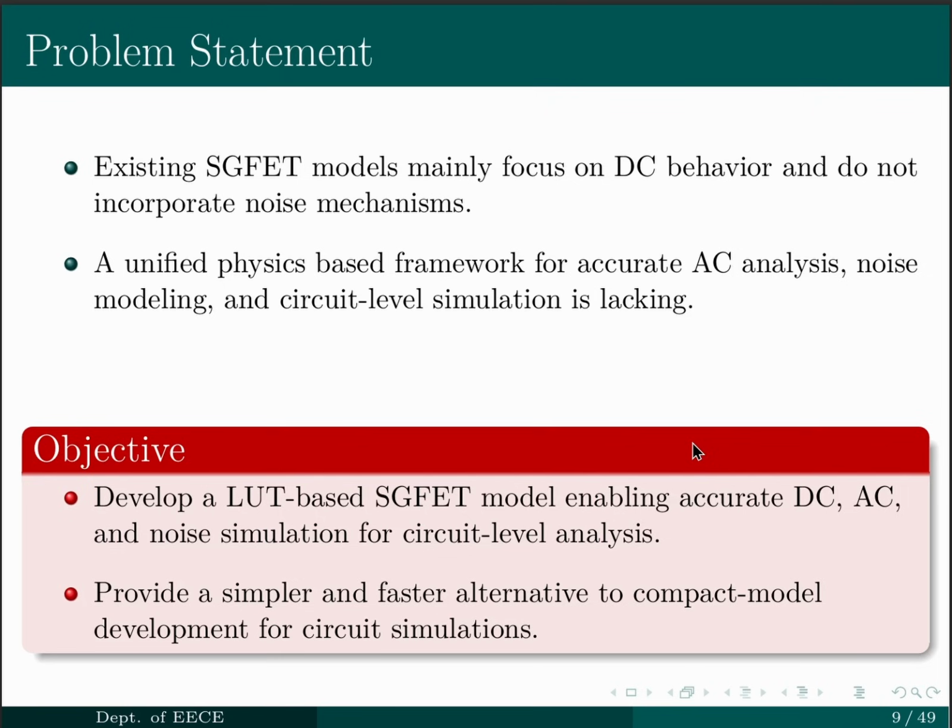And how is it going to be modeled? First, the LUT based SGFET model is going to be developed, which will be simulated for the DC, AC and noise simulation, and for the circuit analysis. The LUT model is used because it provides a simpler and faster alternative to develop the model for circuit simulation, which will take less time than the compact model.